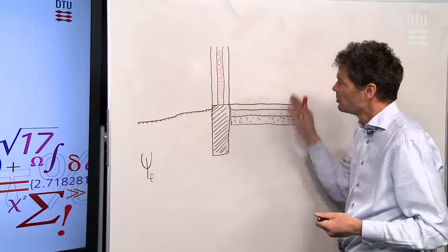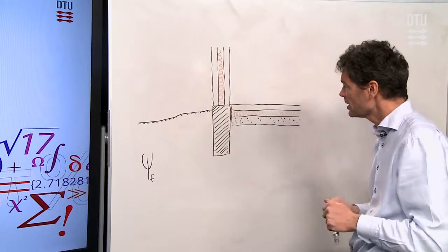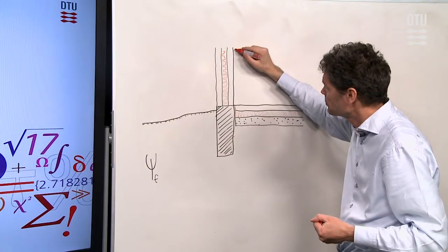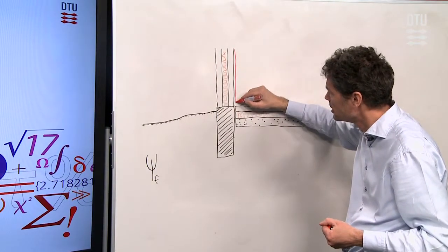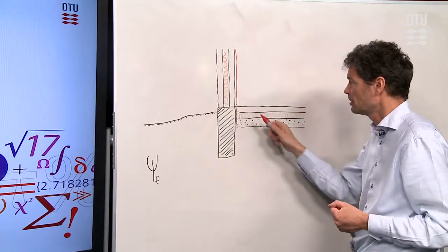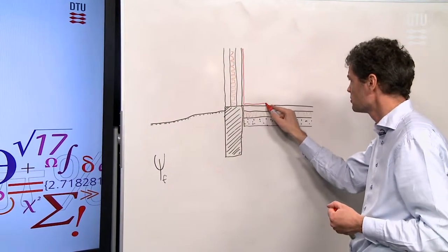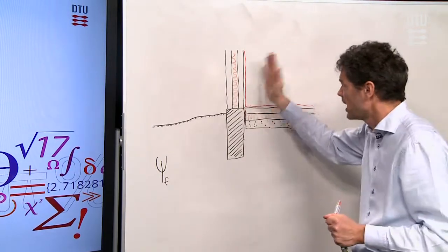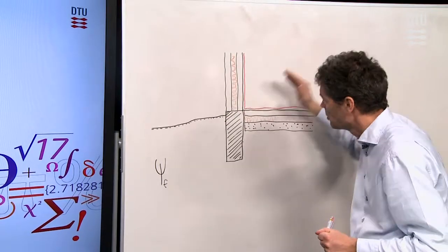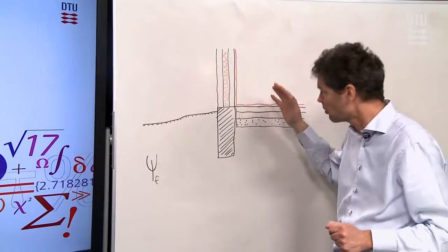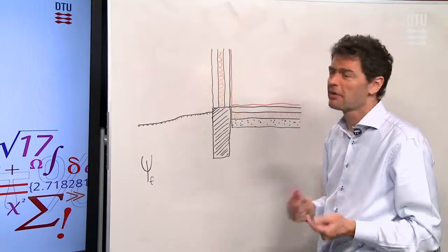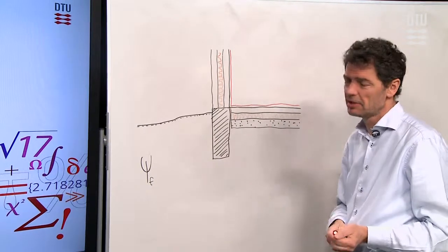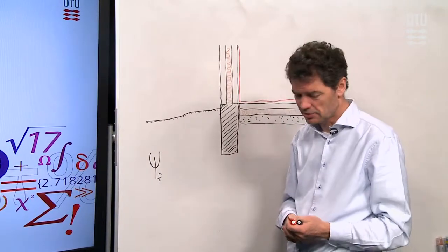So in this geometry, we should calculate the whole domain. Then we should subtract from that the one-dimensional heat flow through the wall. So we're interested altogether in the heat flows through the wall, and likewise also in the heat flows going into the structure through the floor. Those two red lines together, the heat fluxes over that, in total give the total heat flow through the whole system, and then after that we subtract, as I said, the 1D from wall and floor. That will give us the psi value as shown here.